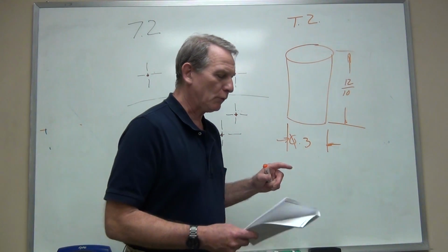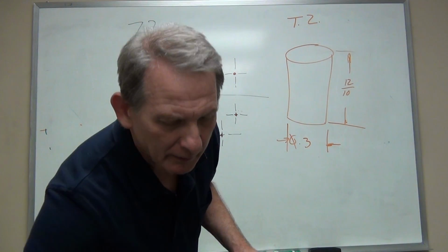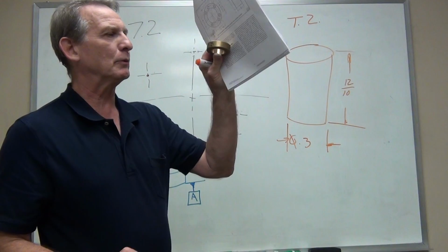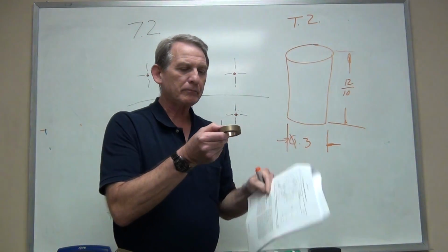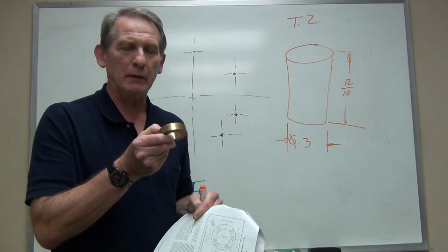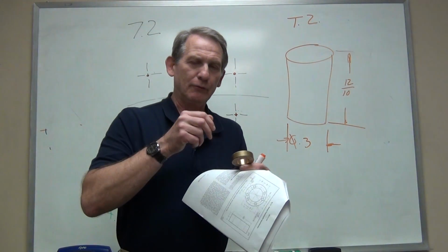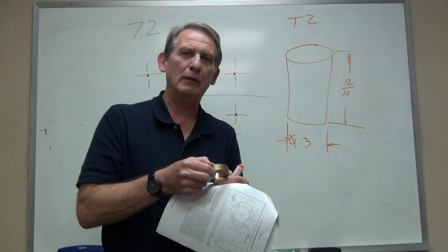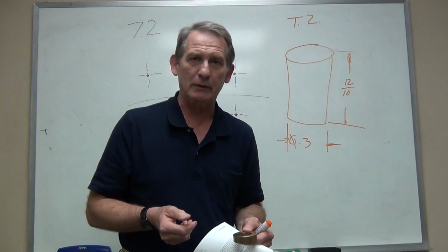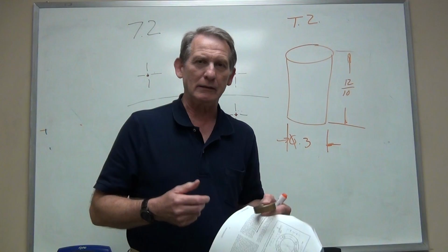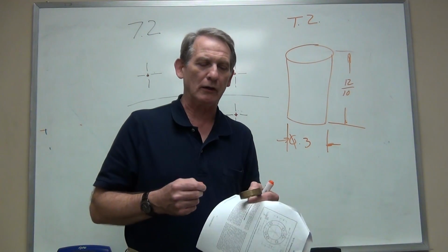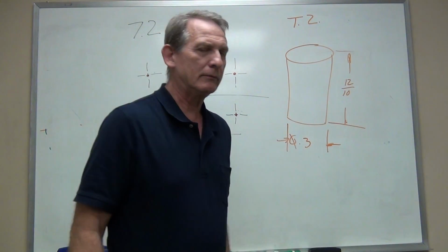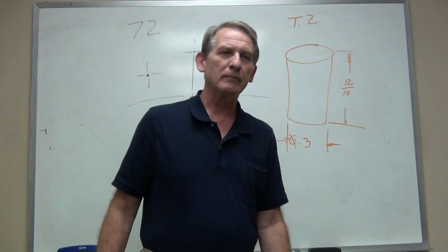So if we make one of these rings that is 12 millimeters thick, that's about a half inch, and so that's pretty close. That tolerance zone would be 12 millimeters long. If the next ring we make, we face it off a little bit short and we end up with 10 millimeters, then the tolerance zone is 10 millimeters long. That is the default. It is as long as the feature itself. So that length is variable, and it depends on the actual length of the actual part.